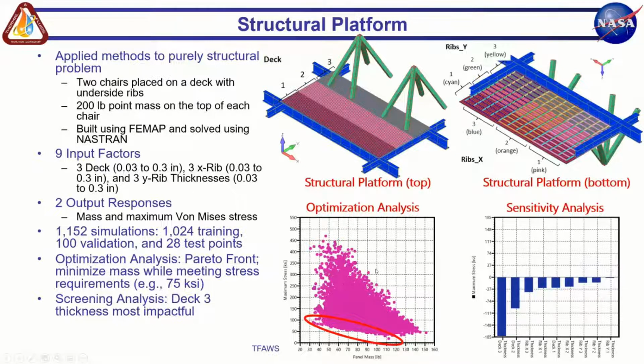And we're looking at, hey, what's the optimal front? We're trying to minimize stress and minimize mass. And so we come up with this Pareto front down here where stress is minimized and so is mass. And then from this Pareto front, we probably want to figure out where best we would want to have our design located.